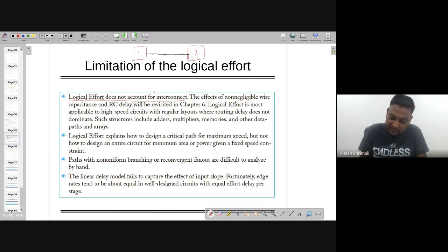However, if you are interested in RC delay, you can read chapter number 6, which is also talking about what I told just now. All these things happen because of the data path arrays, and lots of things are there which are going to act as an antenna, or will have path resistance, it will also have the IR drop, it will also have the inductance.